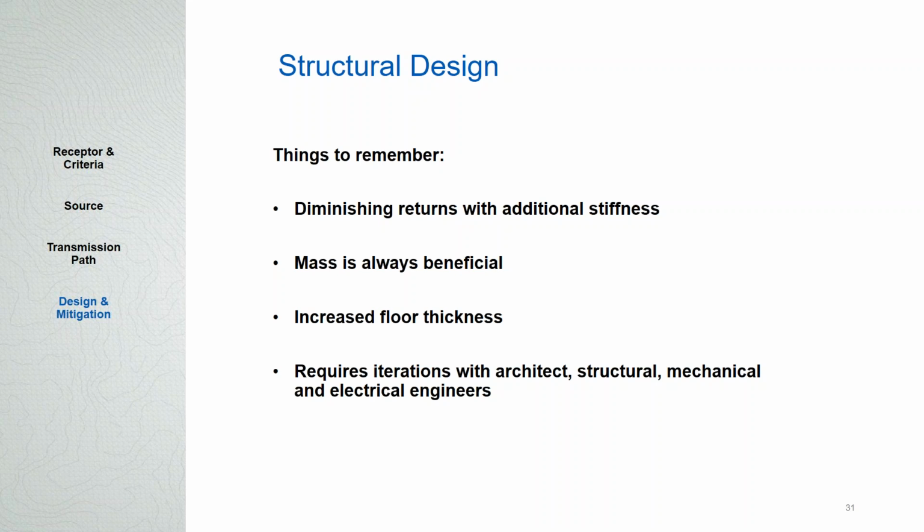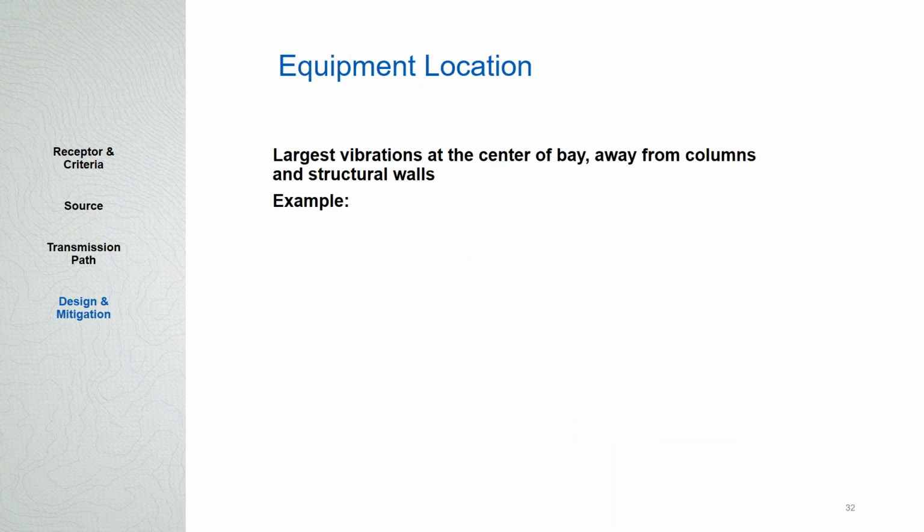There's been one case I can think of where we had such a large beam, we were supporting an MRI, I think it was 3 feet deep, that they had to actually run the duct through the web of the beam. Right? Yeah, they asked, does that affect things? And we looked into it and it didn't affect things that much, so they put the duct through the beam. So preferably, I think we'd like to avoid that, but occasionally it's what had to be done.